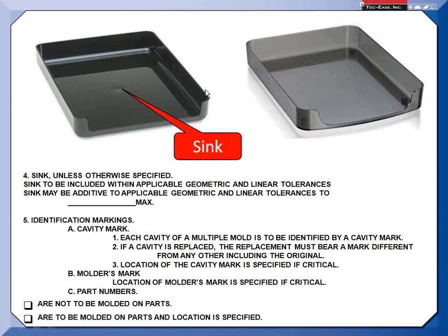Now, those ejector pin marks have standing flash, and if you're familiar with chrome plating, that sharp standing flash will attract that chrome and really emphasize those ejector pin marks. And I saw the brochure, and immediately I said, what idiot didn't specify on the drawing where ejector pin marks should go? Fortunately, it wasn't him. But he said, yeah, I know, I'm not too happy about that one. So try to think about these things with this sort of part.